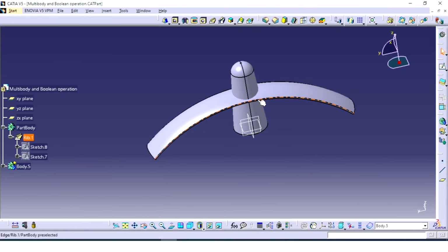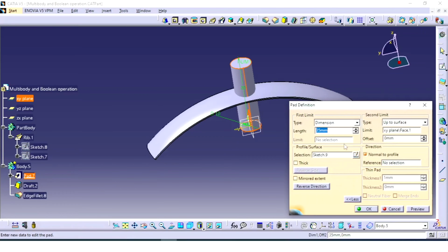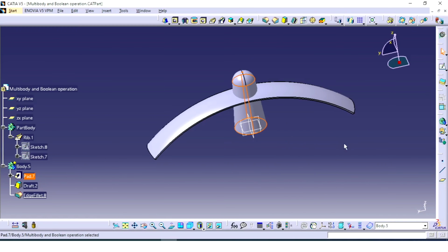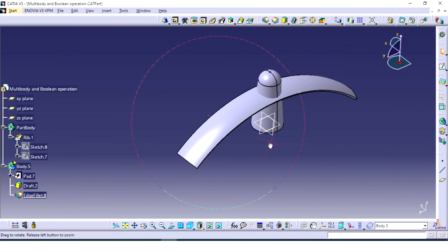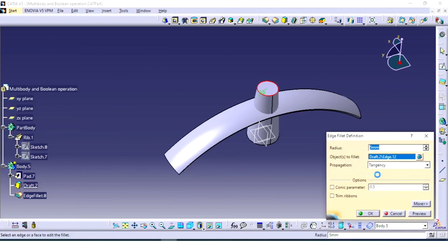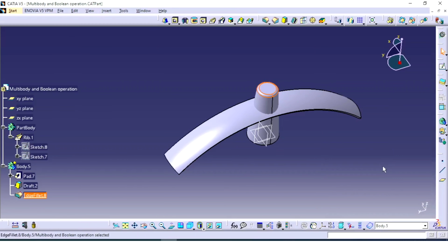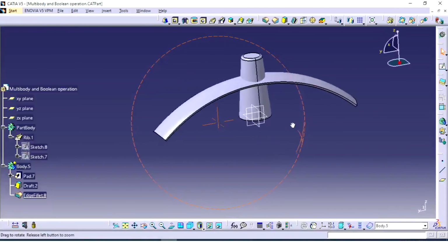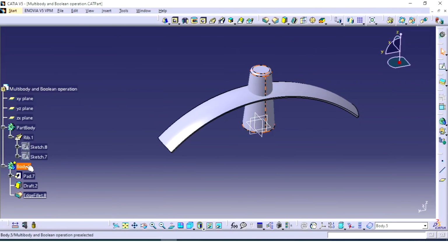Okay, here I want to use the union trim operation. So what will happen? We will see it. I will make the height 30 mm. Let's make it. Okay, and fillet, make it 1 mm. Now I have two bodies.